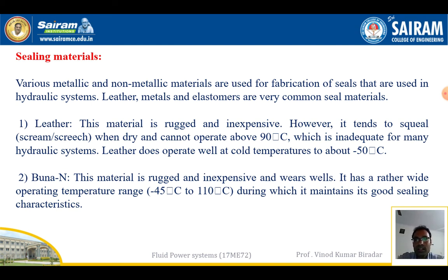Normally leather material is rugged and inexpensive. However, it tends to scratch when dry and cannot be operated above 90 degrees centigrade in a hydraulic power system, which is inadequate for many hydraulic systems. If you use it above that, there is a chance of damaging the parts. Leather does operate well at cool temperatures, down to about minus 50 degrees centigrade.